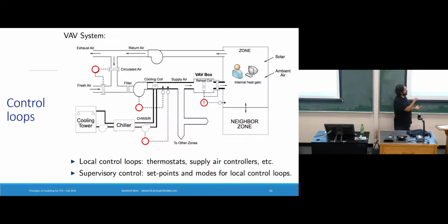So how does it figure out what to do and how much to open this valve, how much to reheat? It all happens based on the thermostat setting, right? So you have a zone where you will have a desired temperature setting, and then this thermostat not only measures the desired reference, it also measures the actual temperature at that point, wherever it's installed.